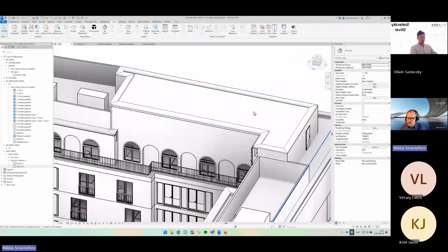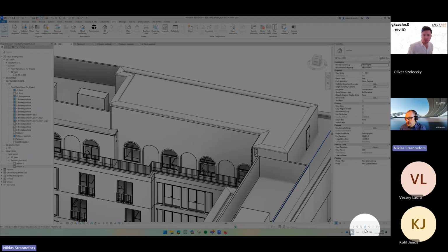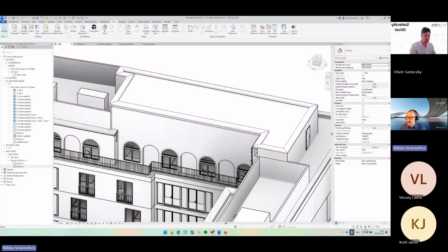How we do it is we go into 3D, we tab. Because it's a floor, you can turn this one on, which is down here, called selection by face. As long as it doesn't have a red X on it, you can select by face. It's next to the move symbol to the left. You have the selection by face. Then we just go into the 3D and use tab until you see the roof. In this case, it's the floor.